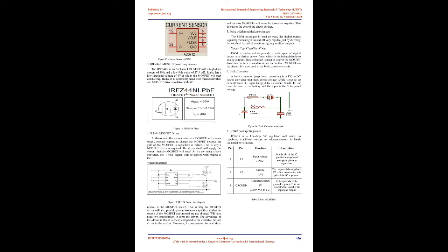PWM charge controller. PWM controllers are similar to series regulators, they use a transistor instead of a relay to open the array. By switching the transistor at a high frequency with various modulated widths, a constant voltage can be maintained. The PWM regulator self-adjusts by varying the widths, lengths, and speed of the pulses sent to the battery. Unlike the on/off charge controllers, which instantaneously cut off the power transfer to minimize battery overcharging, PWM regulators act as a rapid on/off controller constantly.